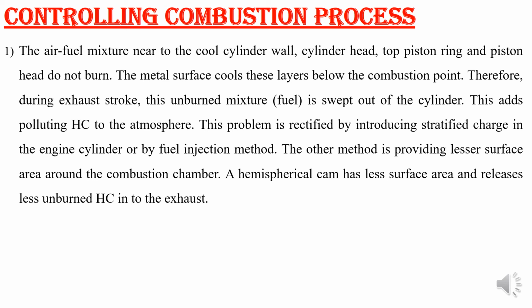Air fuel mixture near the cool cylinder wall, cylinder head, piston head or piston ring does not burn under cold conditions. When the engine is starting, all the components are cold, so most of the fuel that contacts this cold chamber material won't burn. The metal surface cools this layer below the combustion point. Therefore, during the exhaust stroke, this unburned fuel mixture is swept out from the cylinder. This adds pollution to the atmosphere. This problem is rectified by introducing stratified charge in the engine cylinder or by the fuel injection method.